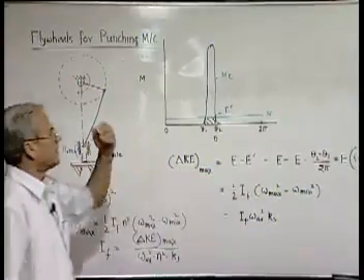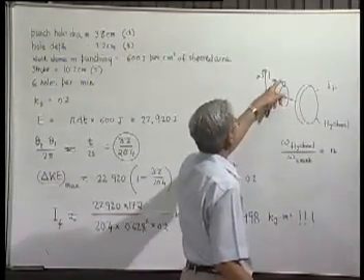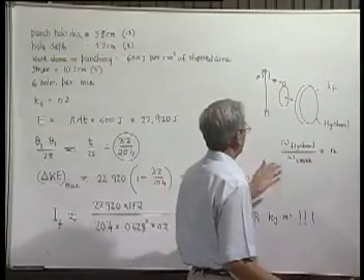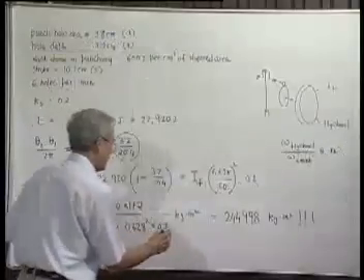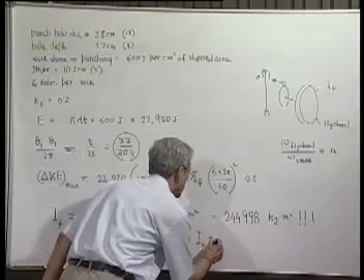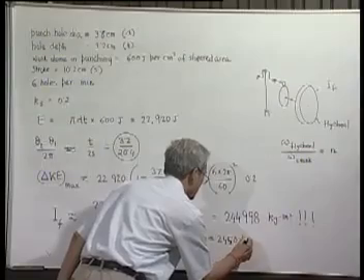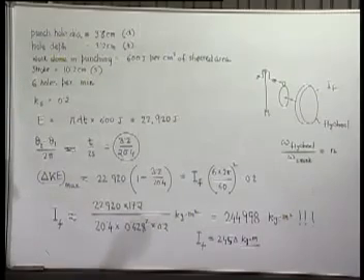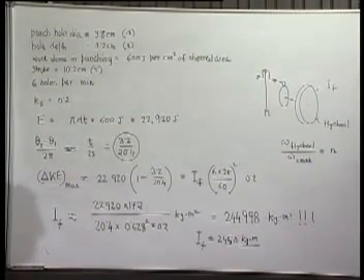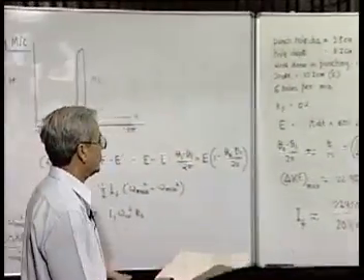So for example, in this particular case, if we put the flywheel on an idling shaft which is connected to the crankshaft by a gear train which gives a ratio of say 10, the moment of inertia of the flywheel required becomes something. That means if you put a rim weighing 2.5 tons at a radius of some meters, which is quite possible, flywheels are big, then your permitted coefficient of fluctuation of speed will be maintained.